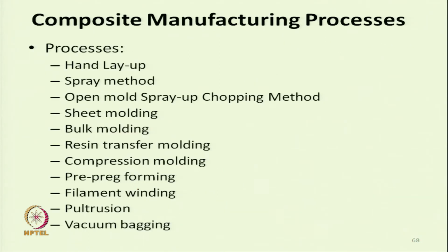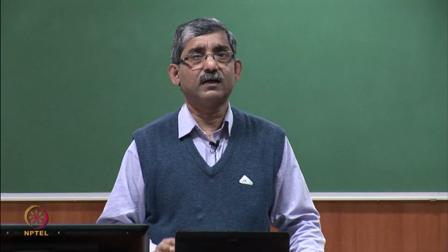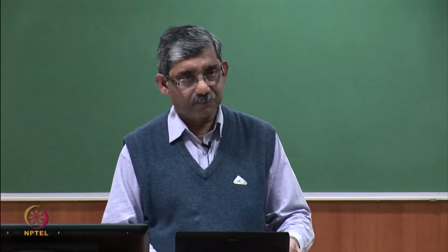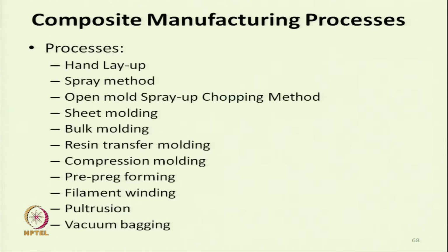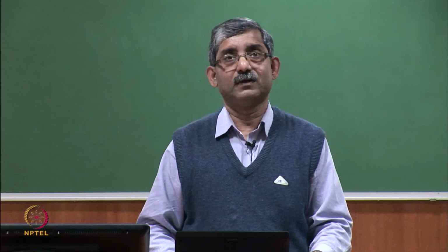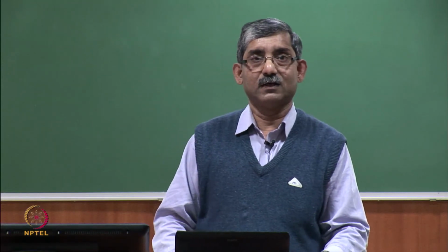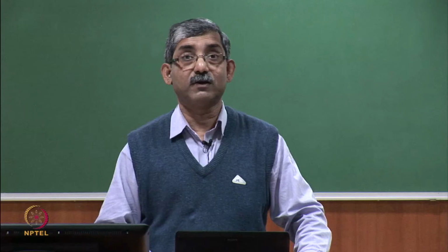Now, we will discuss here the composite manufacturing processes. There are different processes available. Most of the commercial processes we will see at existing process, they are based on the thermoset matrix, and the obvious reason is that thermoset matrix viscosity is less. That is why most of the existing manufacturing processes are based on thermoset matrix, and making composite from thermoplastic matrix is very difficult.